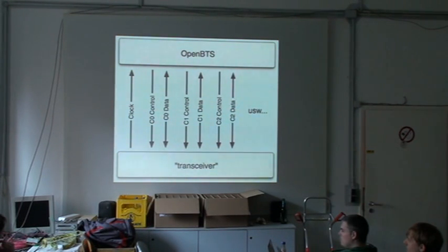And even though we don't use the power level much, it's put in there in case you want to support things like discontinuous transmission in the future. So if you need to send a zero power burst, or if you want to do active downlink power control on carriers other than C0, the protocol will support that